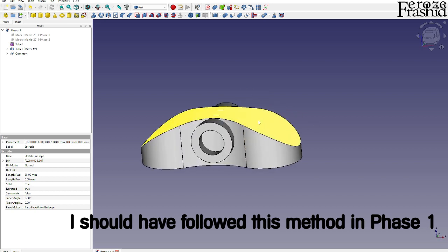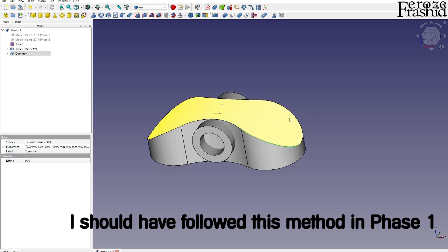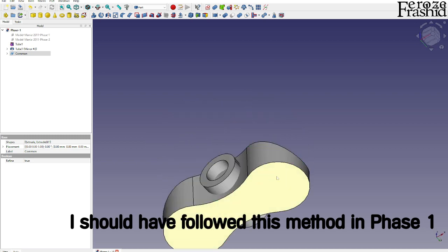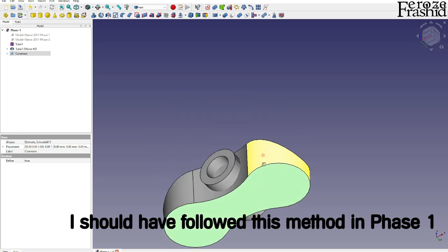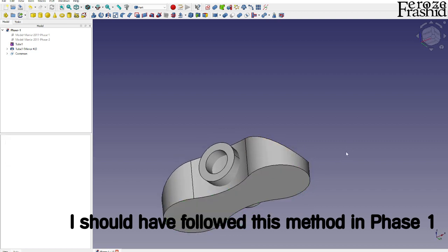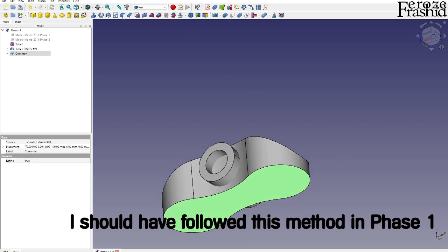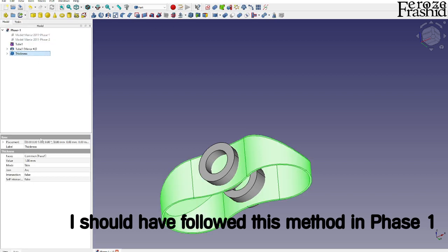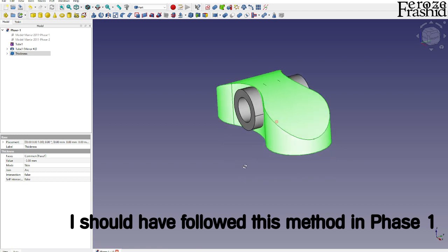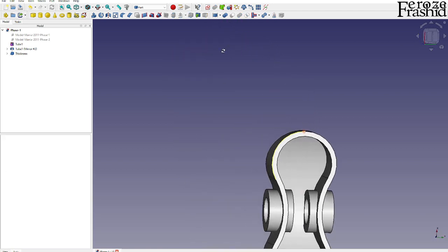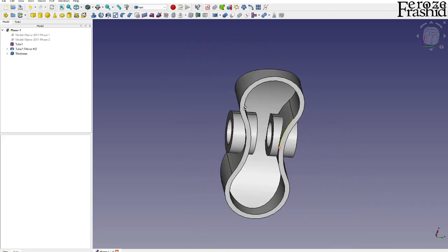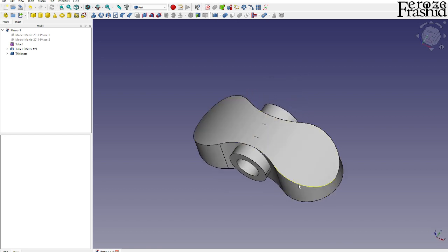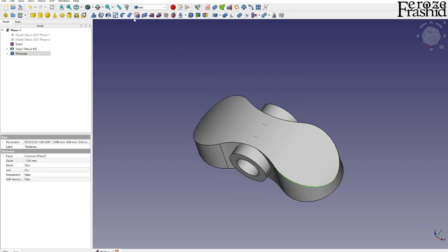Now I have two options. I can go ahead and apply the 6mm fillet right now, and then I can do the thickness, but I have a hunch I'll have to do the thickness first. Let's go ahead and do the thickness right now. I want to keep it there and then come back to the data tab and update it to -3. I don't know why I do that, but sometimes it helps. And we have the thickness tab applied to it, so we have the shell prepared. Now I can go ahead and do the outside, that 6mm fillet.